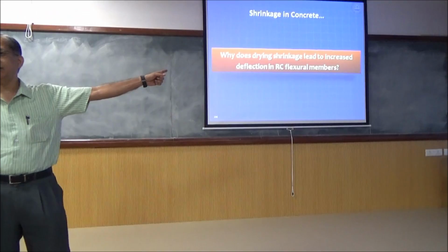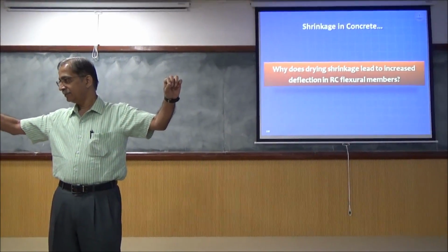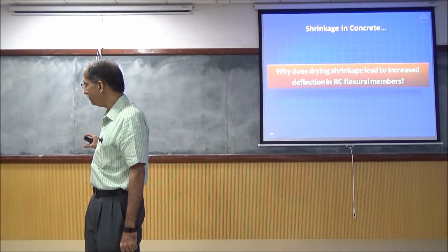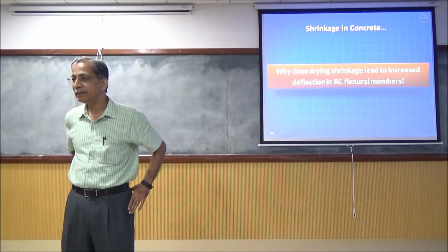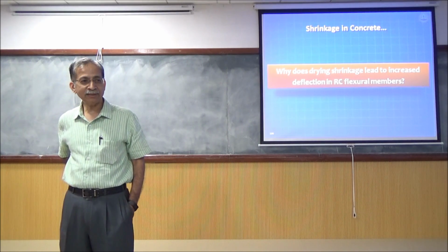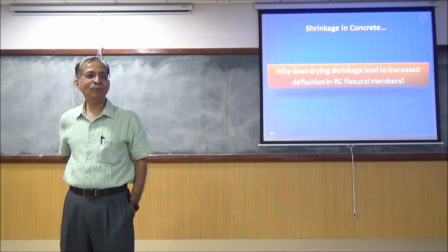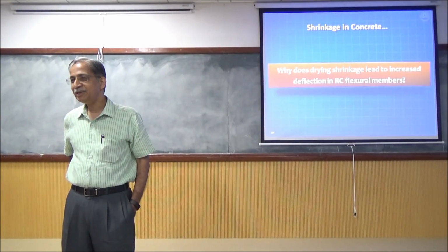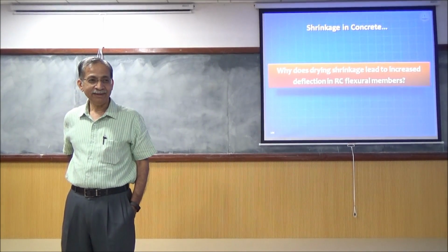This is a good question to ask. I have a simply supported beam. I just keep it there, and we'll measure the deflection due to its self-weight. What's the deflection due to self-weight? Formula? Elastic deflection for a simply supported beam under uniformly distributed self-weight. Your memory is very full, but you didn't finish it. 5WL⁴ by 384EI. Very good.